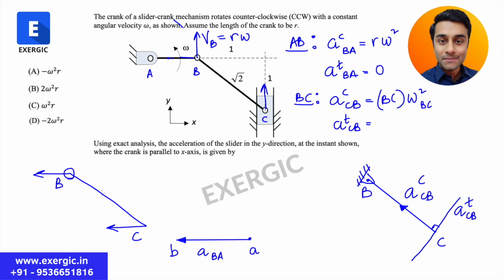Both the ends are moving in the same direction with the same velocity. So all other points on this link also will be moving in the same direction with the same velocity. So this link is basically performing translational motion and not rotational motion. So omega for such a case will be 0. Recall, this is the example that we have solved earlier. Same situation we have here.